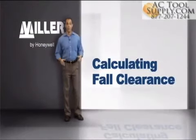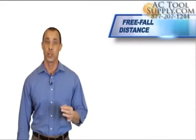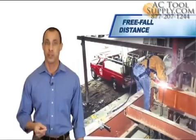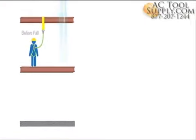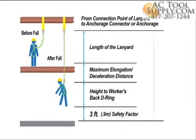Fall clearance calculations are vital in selecting proper anchorage points and connecting devices, and to avoid striking a lower level or obstruction in the event of a fall. Free fall distance should be limited to the shortest distance possible. This is never more than 6 feet when using a shock-absorbing lanyard, unless using equipment designed specifically for free falls over 6 feet. When calculating fall clearance required for a shock-absorbing lanyard, the following variables must be considered: the original length of the lanyard, the maximum elongation after shock absorber deployment, the height to the worker's back D-ring, and a safety factor of 3 feet.